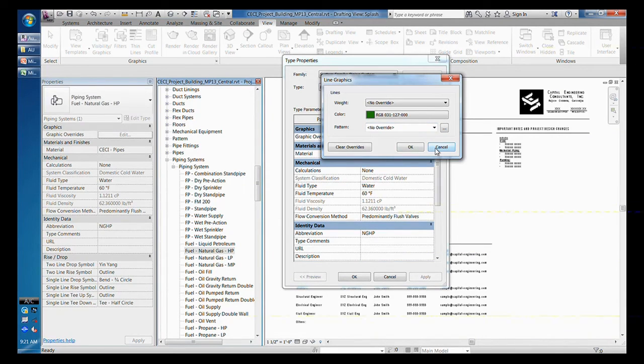And what that does for us is, and it works for us, maybe not for you, coloring your objects globally. Of course, you still have the ability to add filters, to override them through worksets, to override them through color schemes. The system is at the lowest level, and you can add on top of it with any additional colors. We found that works for us. We're using this to control line types and colors, and we're still using filters to control in what view what system is turned on or off. So we separated the two.